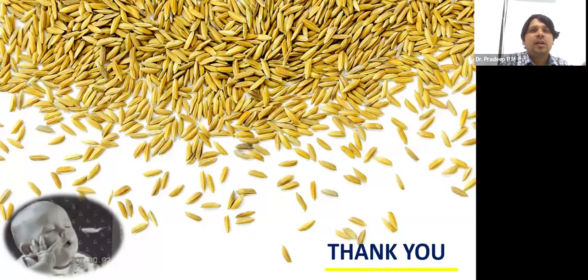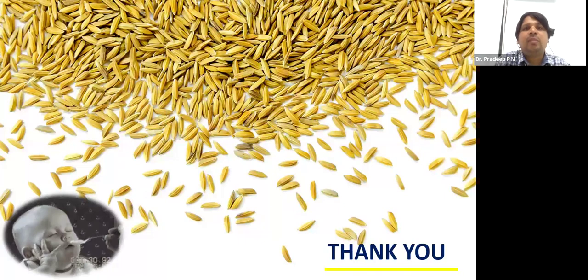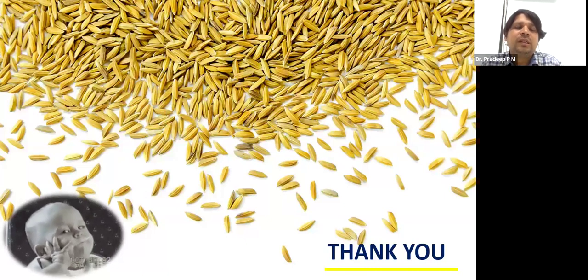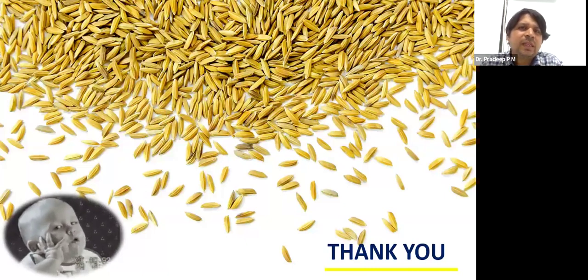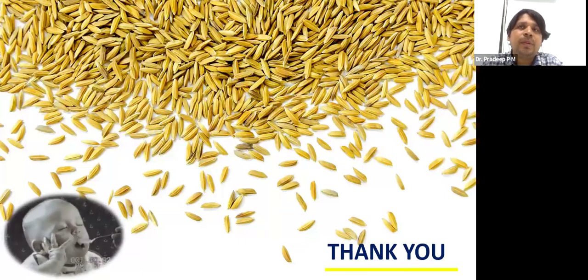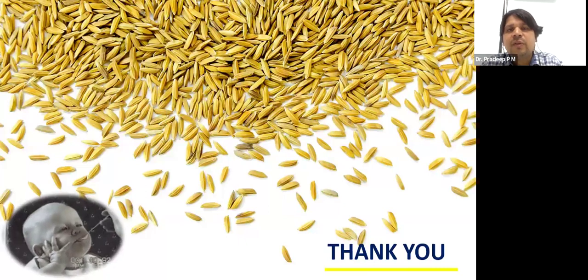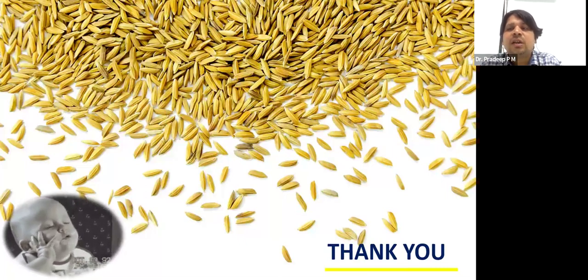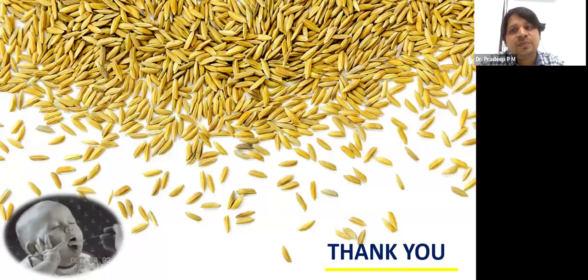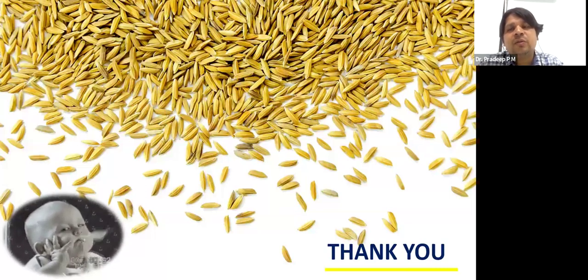That means here there will be multiple dryers. So the paddy passes through multiple dryers in a continuous mode. So the major difference between batch wise and continuous is, in batch wise, the paddy is restricted in a particular dryer for 8 to 12 hours. Whereas in a continuous mode, the paddy moves from dryer 1 to dryer 3 at different stages in a continuous mode. So during this travel itself, the drying is achieved. And this adds more productivity for the plant.